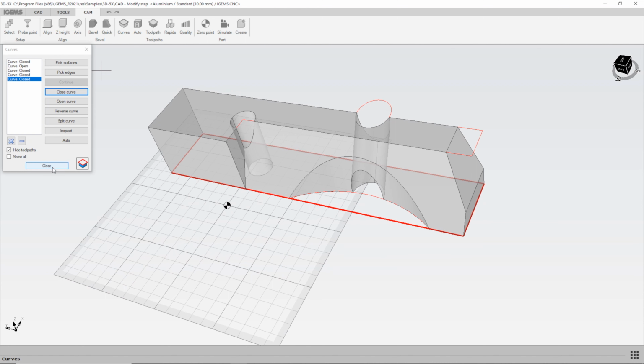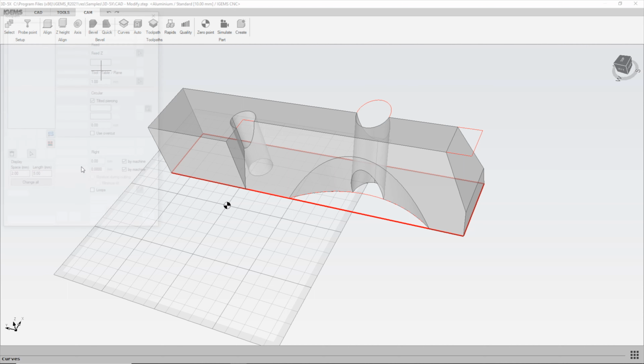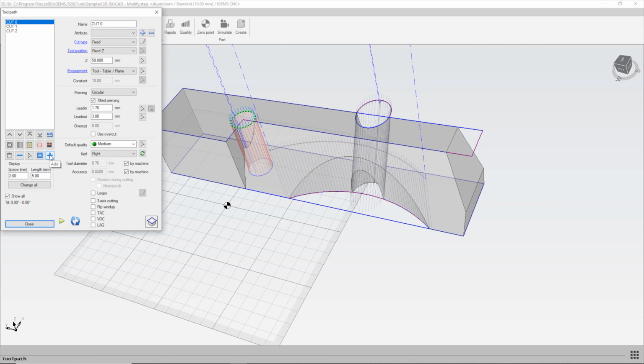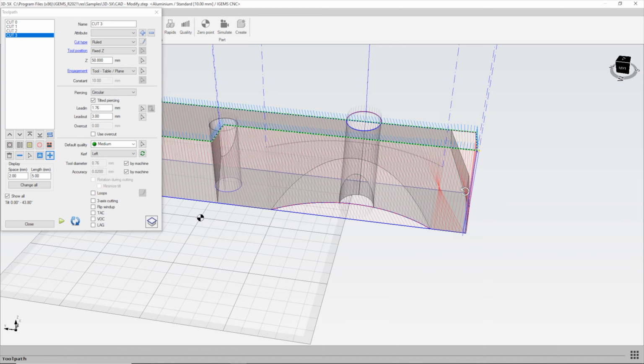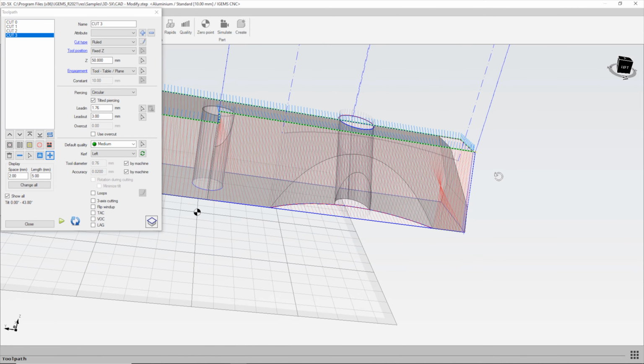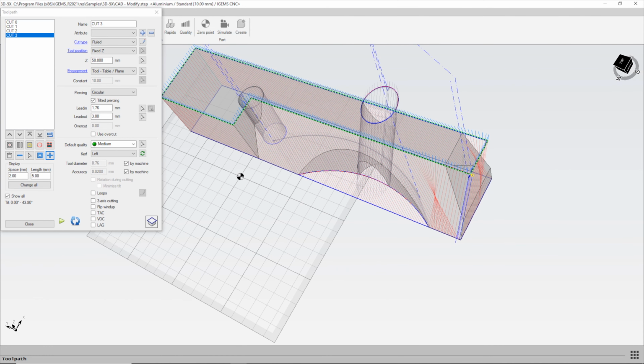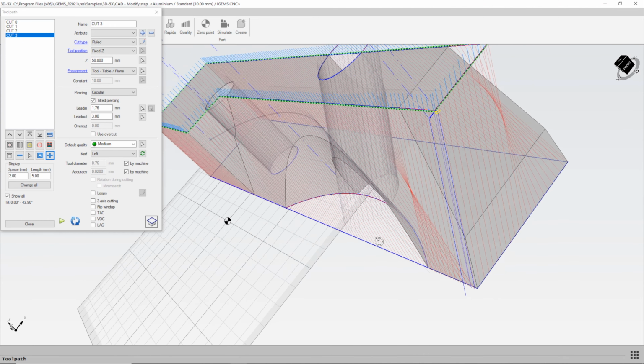So we can go to toolpath, add our toolpath. So we select the top contour, start point, maybe here, and all the way around. So enter. Direction, this direction, bottom contour, right there. Lead in, lead out. So, well, there are some problems here, as we can see.